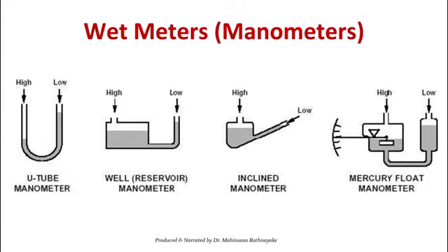In fact, manometers are used as industrial instrumentation also in chemical process plants, right? So there are different types of manometers. One is the U-tube. U-tube, you know, means not the website, I mean the U-shaped tube. That is used for pressure measurement, and from the height difference between the two sides of the U-shaped tube you can find the measurement for the pressure.